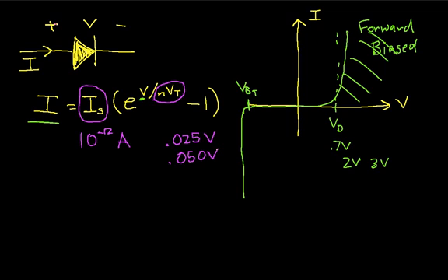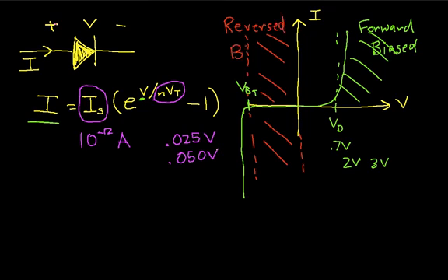And what basically happens is, well, let me put in some terminology first. This region between here and the origin is called reverse biased. And the idea is that the voltage is negative, so the current's very small. And once you get out past this threshold VBT, so you're in this region, this is called breakdown.